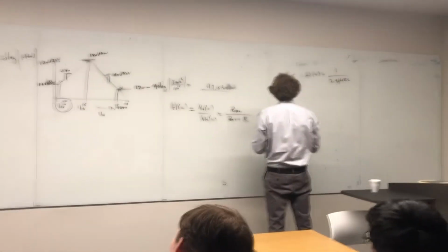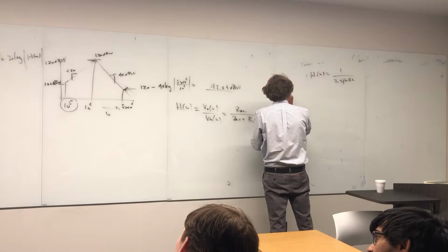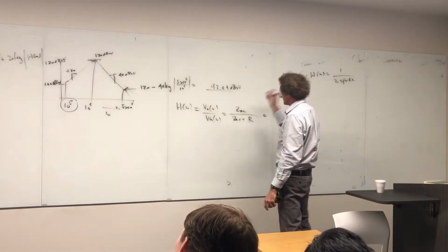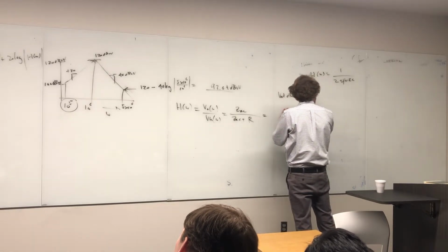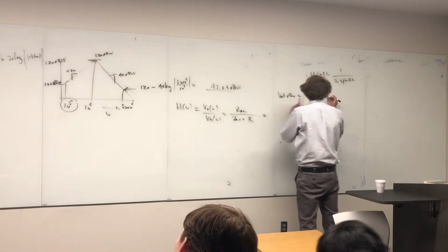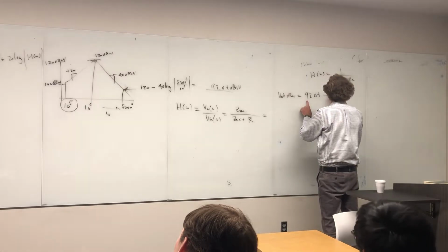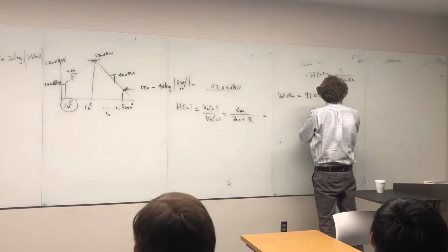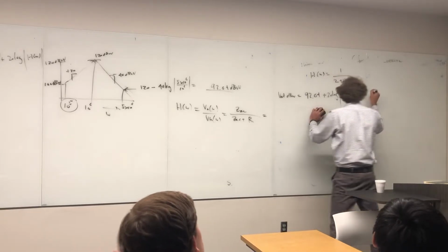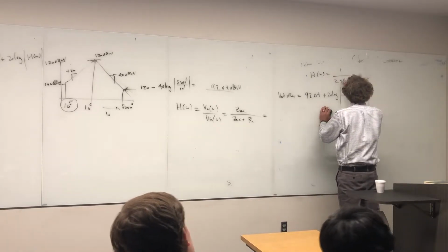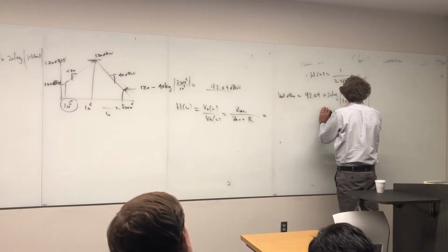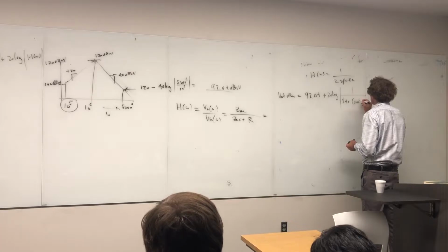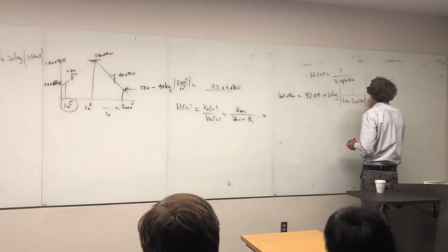That means our V out in dB microvolts would be equal to the value that you got, which was 92.04 dB microvolts. Then it's going to be minus, well actually you can do it plus if you want, but it would be plus 20 times the log of the magnitude of 1 over this, which would be the square root of 4 plus, and then you would have 5 times 10 to the 6 times RC squared, right?